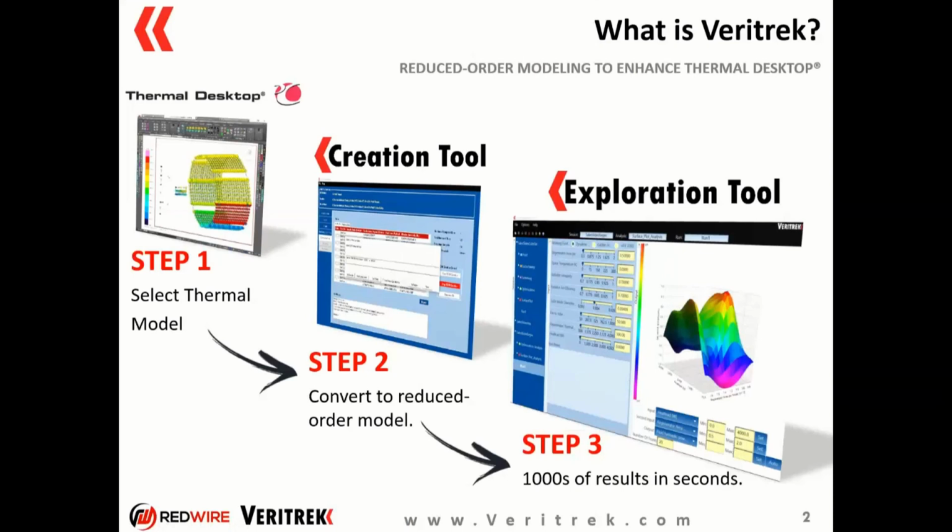We've already talked about it. It converts Thermal Desktop models into a reduced order form. The question is, how does it do that? We break it down into a three-step process. Step one is you start with your Thermal Desktop model. Really, the only restriction we have here is that it has to be Thermal Desktop 6.0 or greater, so we can take advantage of their OpenTD API. And so that's the limitation.